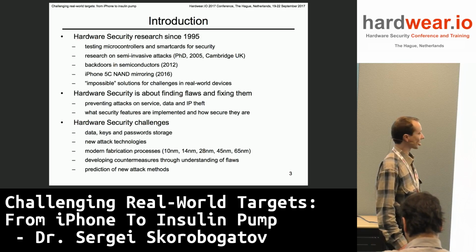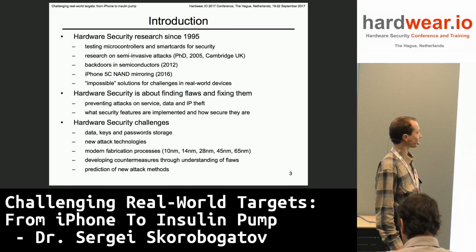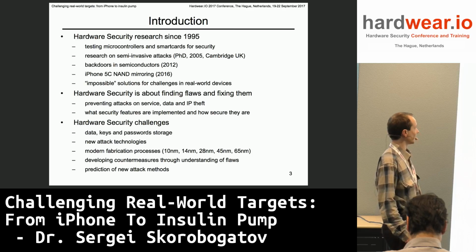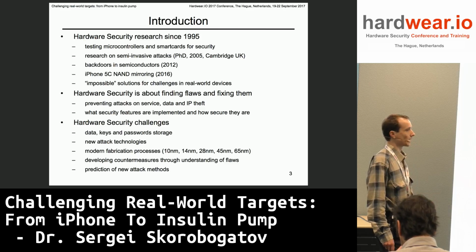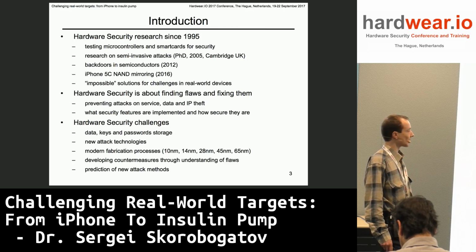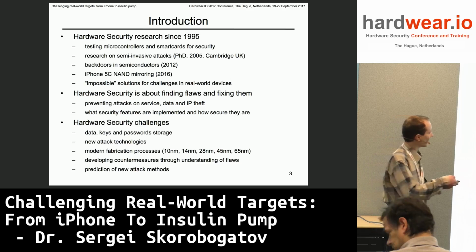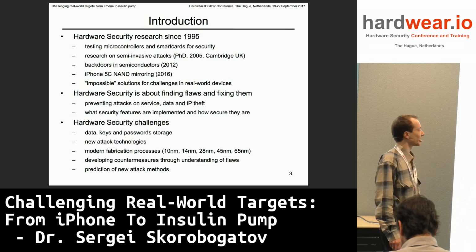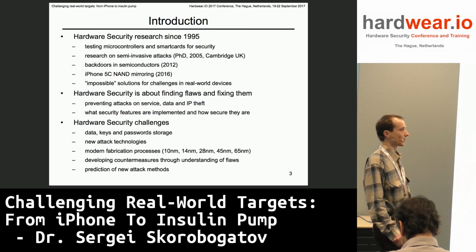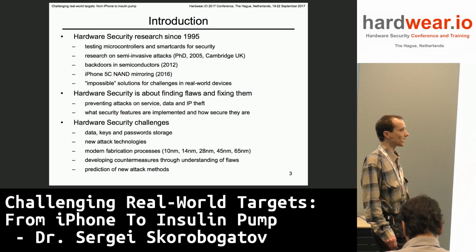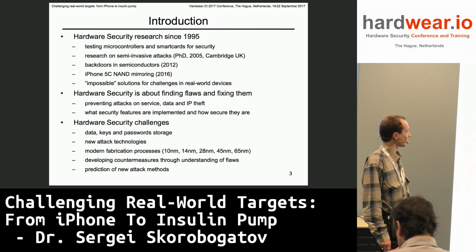And there are lots of challenges in hardware security, such as how well the data keys and passwords are stored. You have to be aware of new attack technologies, and with modern devices you are facing quite challenging fabrication processes, starting from 10 nanometers, while most devices will still be at the far end of about 65 nanometers, and even 65 nanometers, although it looks quite sophisticated, you can still see lots of structures under an optical microscope.